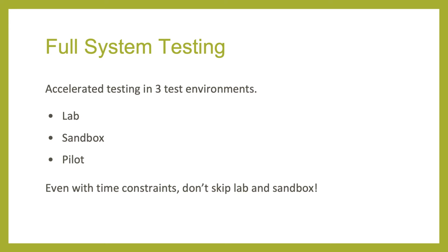The testing approach we take here at FreakLabs is to do accelerated testing of the complete device in 3 test environments. Accelerated testing means that we would, for example, take a sensor reading every 10 minutes instead of every hour, or we would set the threshold closer to the ambient temperature so we can take temperature readings more often. Basically, we want to hammer the system and see when it breaks.